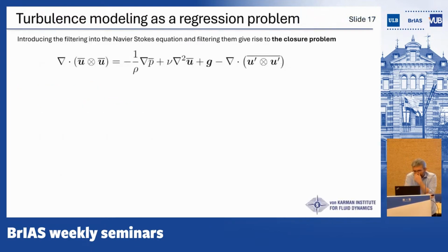So when we talk about turbulence modeling, what do we mean? Now, without going too much into the details, I just want to give you a flavor of the idea here. Usually we have an equation that governs perfectly how our flow evolves. That's the Navier-Stokes equations. And we abandon the idea that we can solve for everything which is happening in the flow. We say, okay, some parts we're going to solve for, other things we're not going to solve for because it's too demanding, computationally speaking.